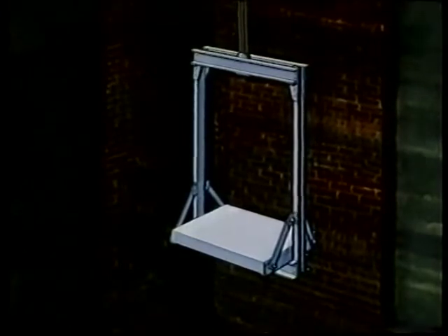The platform effectively spreads the load, so that the cross-member supporting it is in effect a beam under a uniformly distributed load. So this beam has to be designed for stresses resulting from downward bending. The top cross-member, on the other hand, experiences effectively an upward point load at the center due to the ropes. So this beam has to be designed for bending due to a point load upwards.